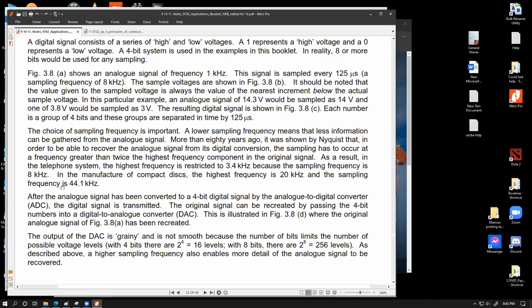But that makes sense. I mean, if you keep the sampling frequency of 8 kilohertz, the maximum allowed audio frequency could be up to 4 kilohertz, but they have preferred to keep it at 3.4 kilohertz. I don't know why they have to take this 0.6 kilohertz gap. I honestly don't know this, but this is very much valuable within the acceptance line.